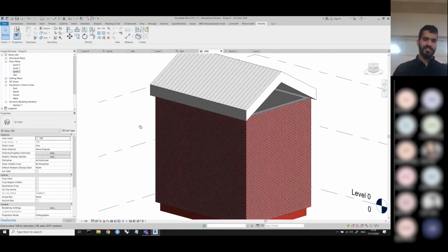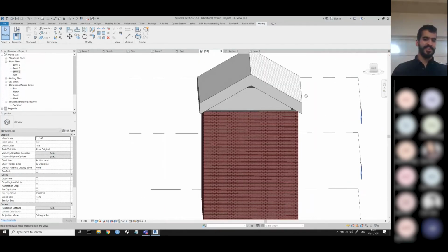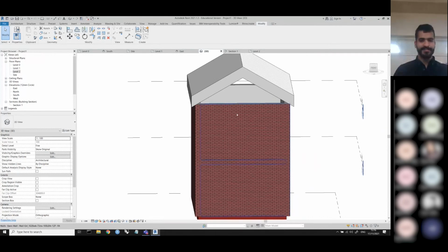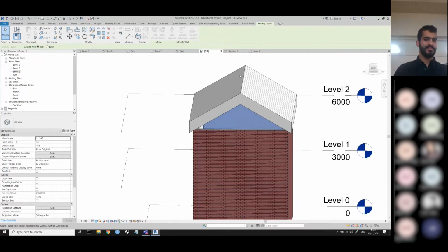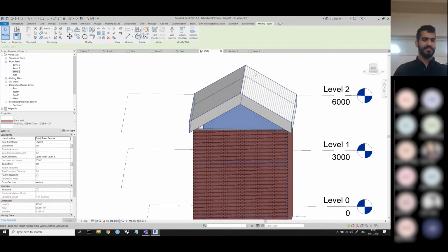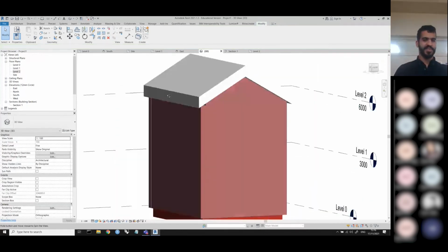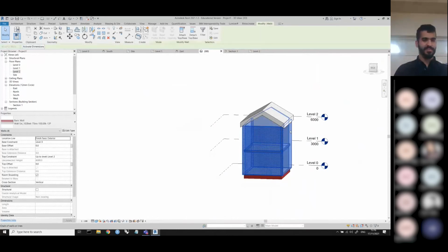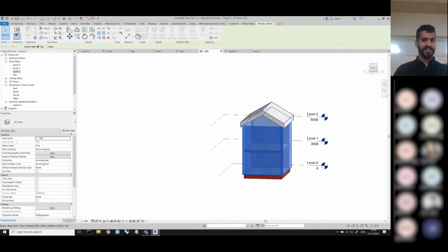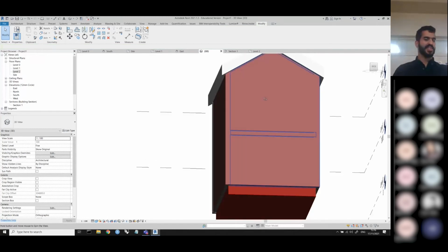So at the moment, of course, we have these two ends that we need to connect, right? So if you click on these two walls, attach top base, click on this. Let's try that again. Actually, I should select all four walls. Yeah, all four, attach top base, and then click on the roof. And you see everything's attached nicely.